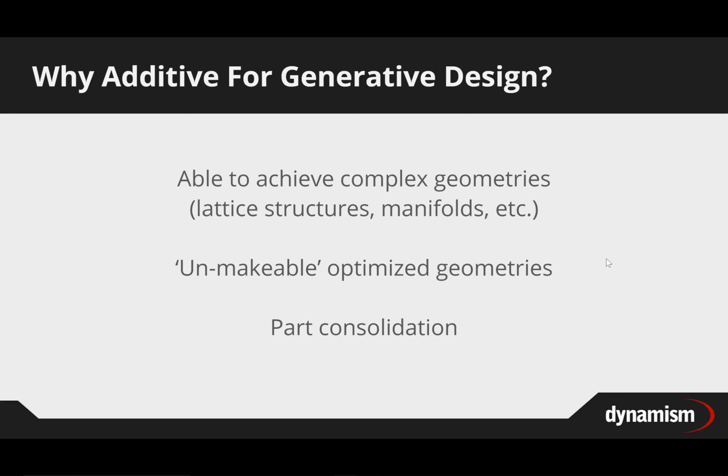There are some other considerations that you will need to take into account. AM can be expensive, depending on the type of technology and what you're trying to achieve. But really, you need to do an internal analysis of this. Other things to take into mind are lead time and tooling costs, and how fast you're trying to get to market if you were doing traditional manufacturing. Another thing to keep in mind is also the size of your part.